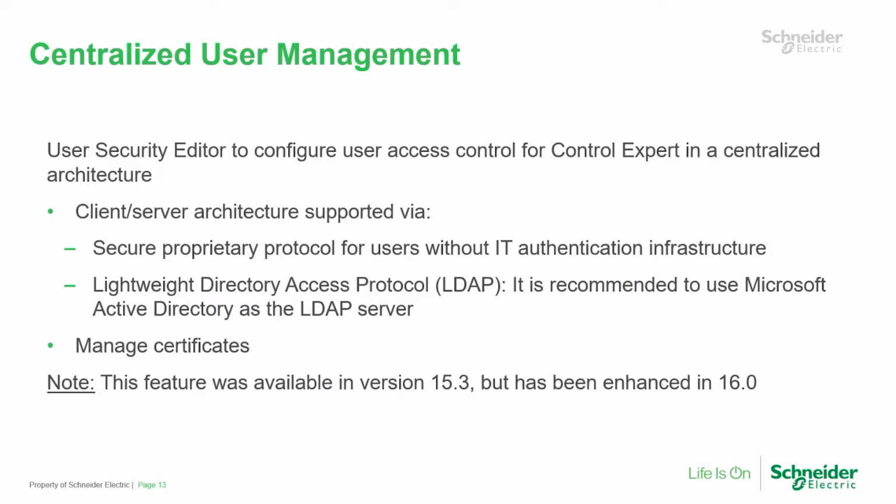But in addition to just using security editor, you can also connect to an LDAP server, which is the protocol used by Microsoft Active Directory, so that people can log into Control Expert with Windows usernames and passwords. So this is a cybersecurity enhancement, but it can also be a usability enhancement for some customers because it allows us to do role-based access control based on a user group.